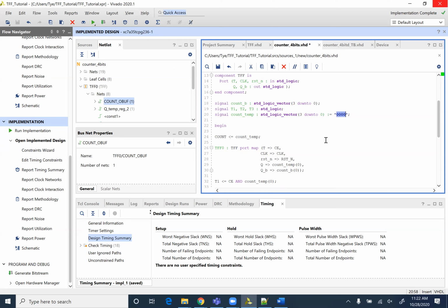Now in my 3610 class, we'll talk about synthesizable versus non-synthesizable logic, and I will harp on the fact that this is not synthesizable. Just because I tell it to start at zeros does not mean it will. This used to be essentially universally true. However, many modern FPGA technologies will be able to synthesize this. Not all of them. And ASIC technology, if you're designing chips for VLSI courses, for example, will still not synthesize it to this day.